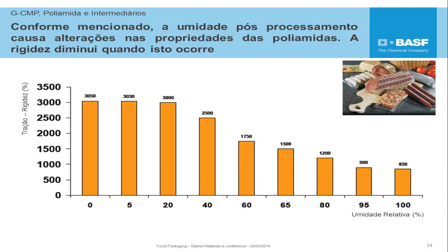It is observed that the process of immersion in water after the injection significantly improves resistance to break of parts after injection, thus changing the apparent glass behavior to a pseudo-elastomeric behavior, supporting the normal post-injection handling process during stock, packing and transport.